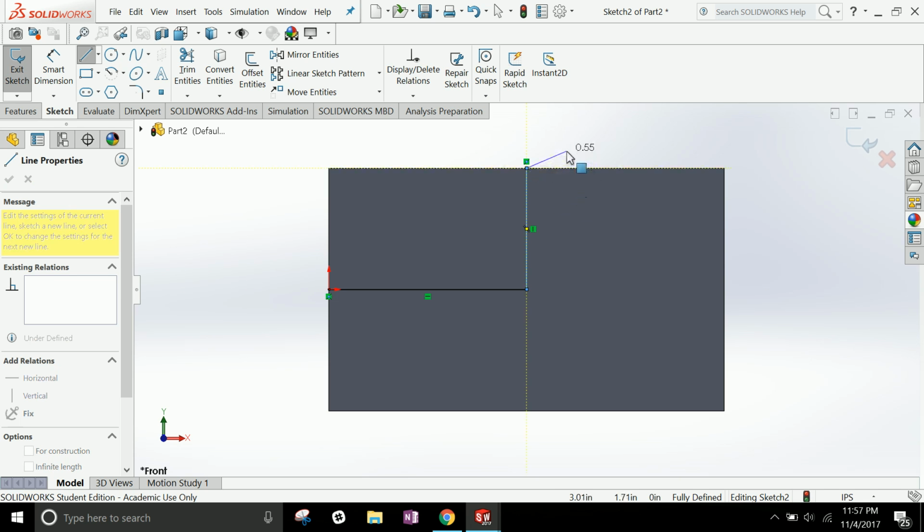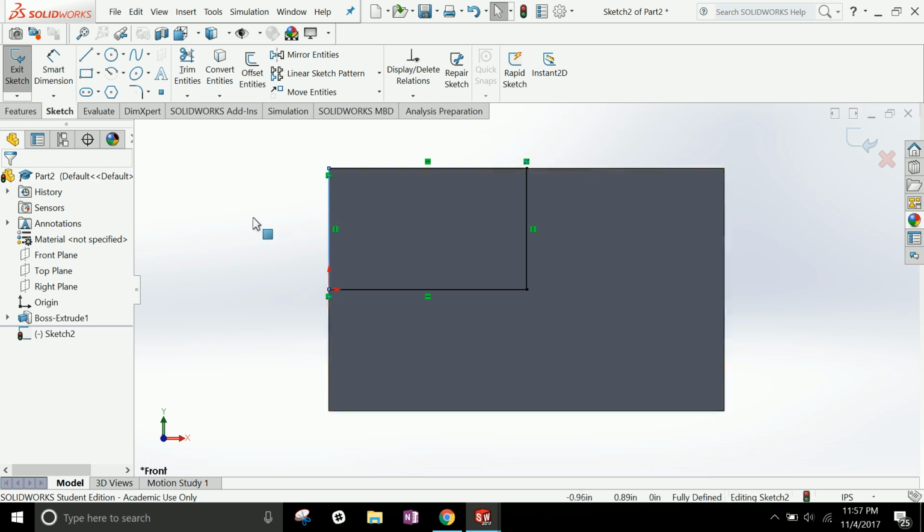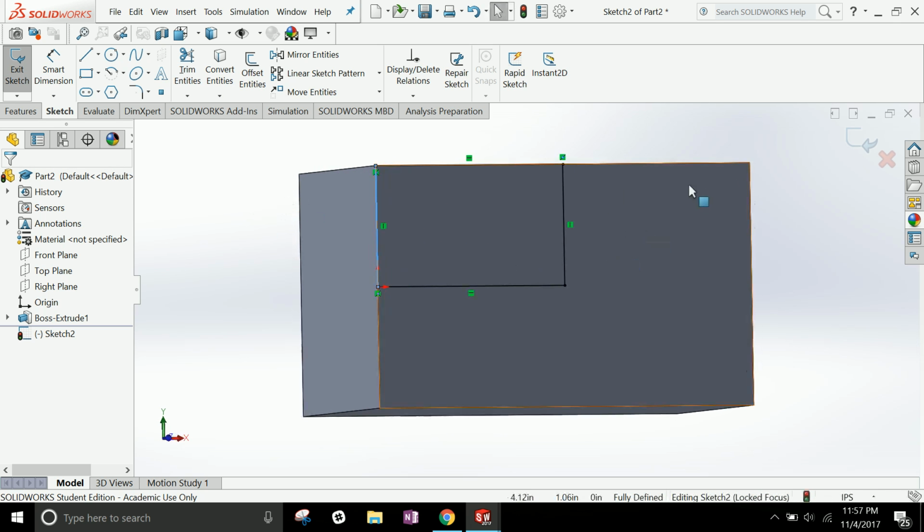So right now I have this simple sketch, and I'm going to go ahead and enclose this. Enclosing your sketches, your contour lines, is going to be important whenever you want to use an extrude feature. Okay, because you can't extrude something that doesn't connect to itself. So now I've made the sketch. I'm going to click the green arrow, and I have this sketch. Now what I'm going to do is somewhat the opposite of what I did last time.